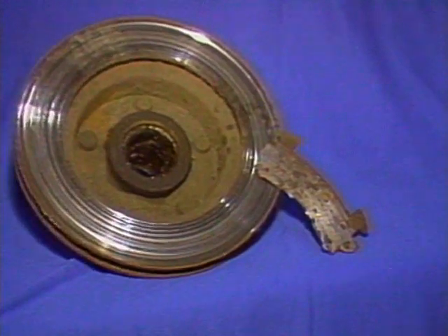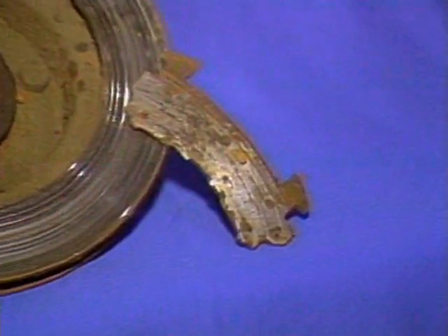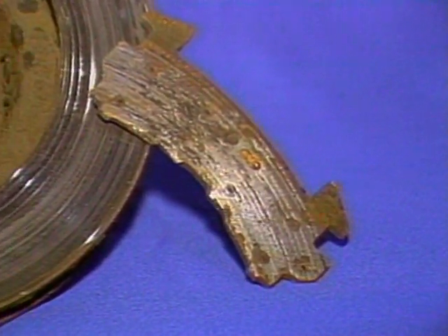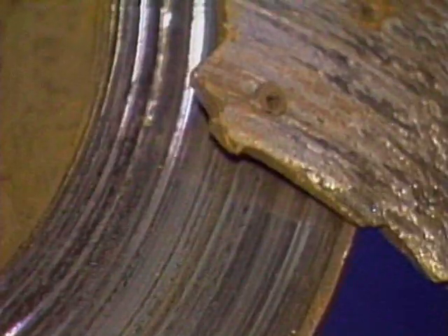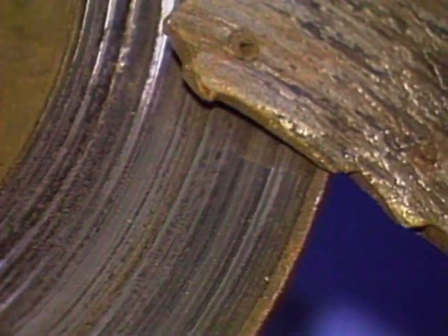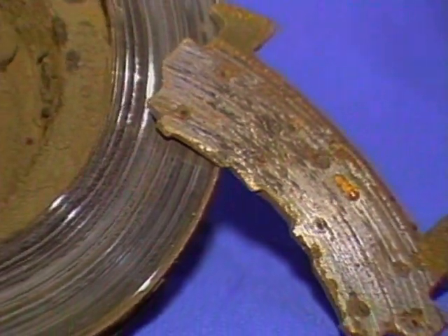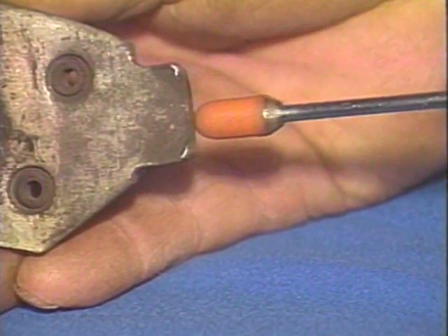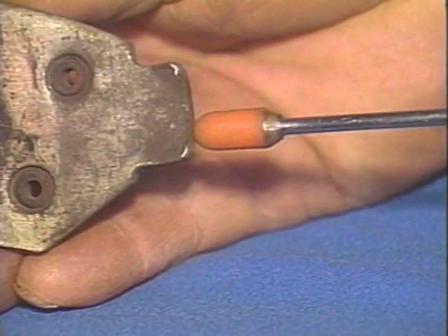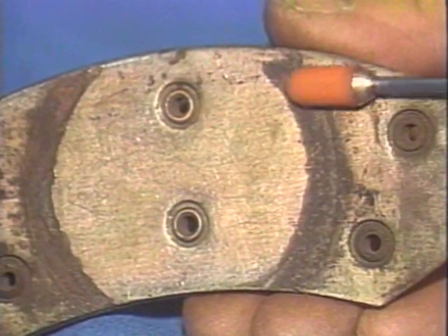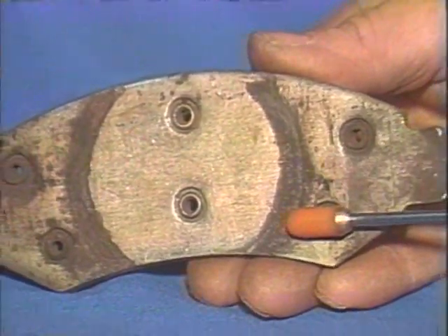Here's an example of how a driver abused his brake system. The metal part of the pad rubbed against the metal part of the rotor with catastrophic damage. The customer had to purchase new rotors and drums, a very costly mistake. Squeaks and rattling can also result if wear makes a brake pad loose in its caliper. The pad can also make squeaking noises where it contacts the caliper piston.